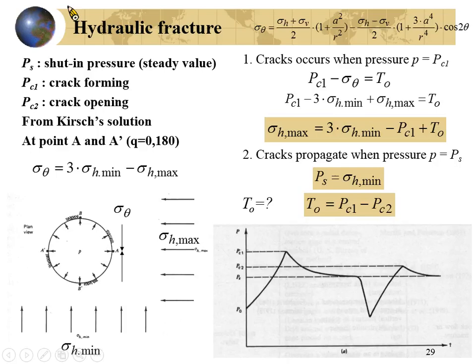For example, if you find the fracture occurred on here and on here, and we know here is the east and here is the west, then where is the maximum principal stress? Can you tell me the principal stress direction of the maximum horizontal stress? It would be in the east-west direction. It would be the maximum principal stress direction.